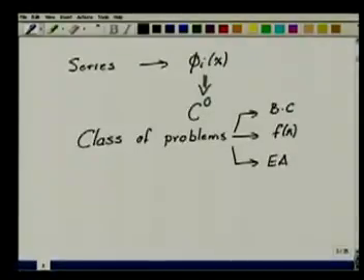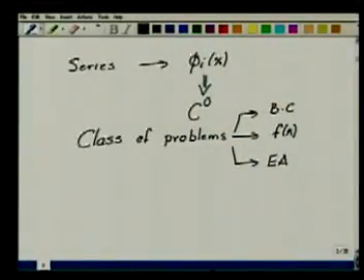And for the point load, this phi I with jump in derivatives was needed, or with material interfaces it was needed, and it comes out also from our requirement, minimum requirement for the left hand side to be finite. So that is the reason why one chooses one type of basis functions for a given differential equation. We will see later on when we go to the beam problem that these basis functions, the definitions of these are going to change. There again we will see what is the minimum requirement for which we have to define these basis functions. So don't think that this whole process is arbitrary in nature.